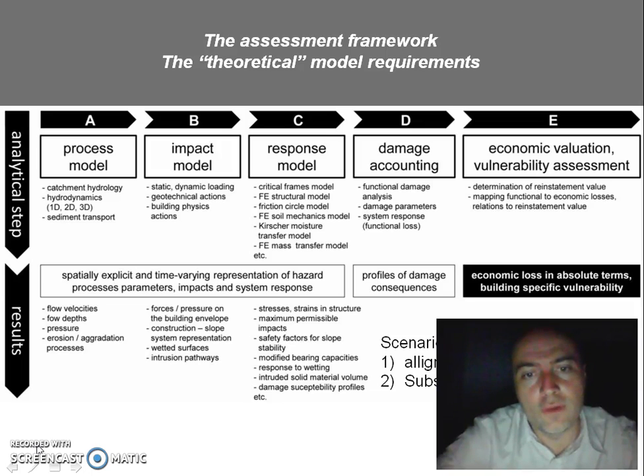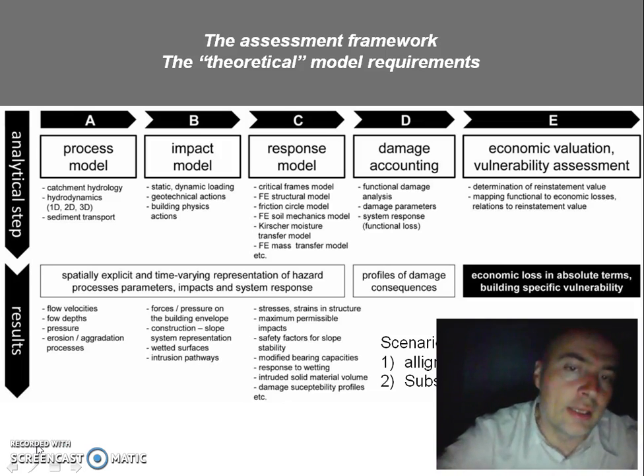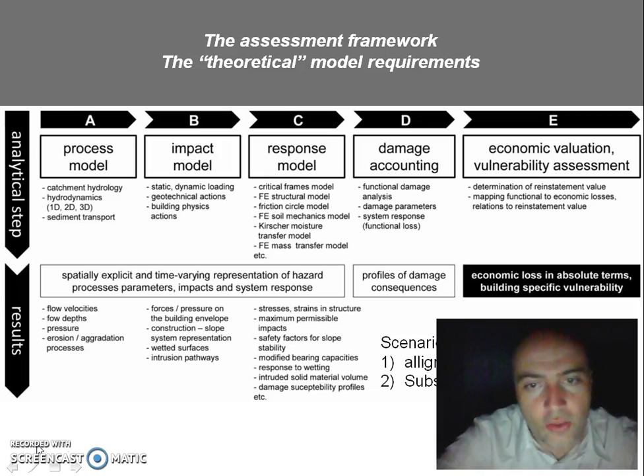In case of hill slopes, we apply safety factors for slope stability. That means that if the ratio of the destabilizing factors to the stabilizing factors is inconvenient with respect to the chosen safety factor, we conclude that the slope is going to fail. Otherwise, we conclude that the slope is going to remain stable.